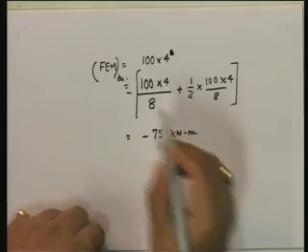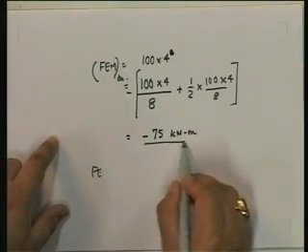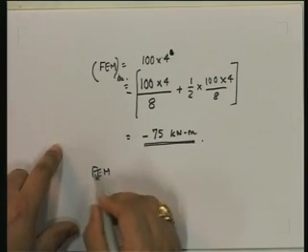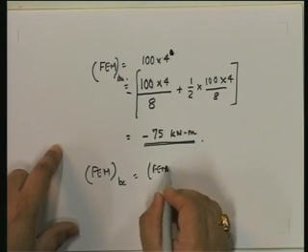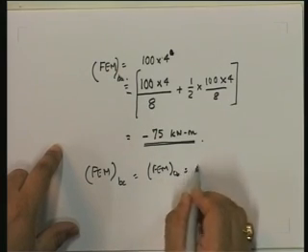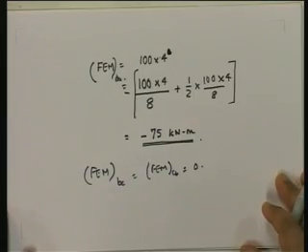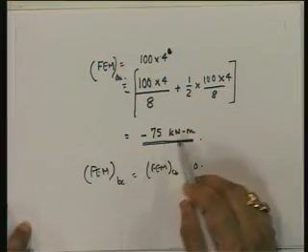This is BA and FEM. So please make the change that in the previous case also this is minus. The same, there is no difference in the fixed end moments. In other words, by changing the structural configuration, the fixed end moments in the two members are not changed.